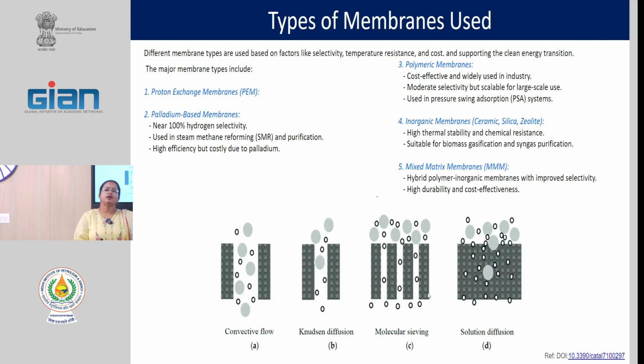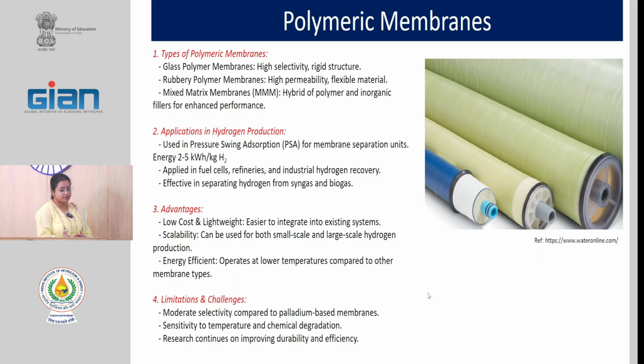So, it can be more scalable. We are infusing some inorganic material into the organic matrix for the mixed matrix membrane, making the membrane more porous but more selective at the same time, and also making it more cost effective, so that we can go for a more scalable approach, with more application in real life. That is why many researchers are mostly focusing on this mixed matrix membrane, or what we call a composite membrane in general.